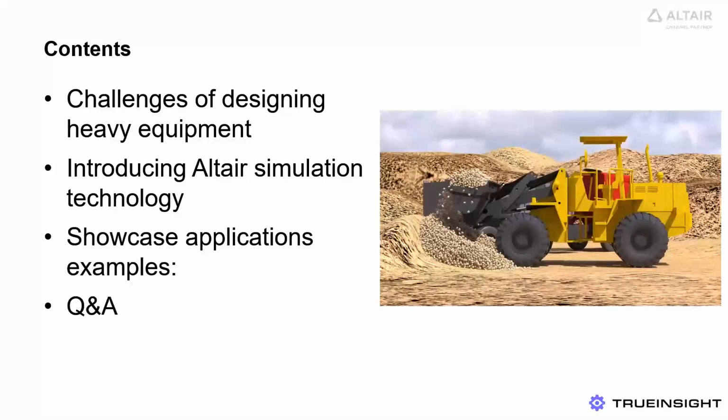Traditionally, most of the bulk materials handling and processing operations, including mobile equipment, are empirically designed, and the measurements of input data into models, such as force and pressure on equipment, are difficult to obtain, time-consuming, and costly. Typical bulk material problems faced include blockage, material buildup, equipment downtime from broken parts, and equipment wear, that all ultimately lead to lower productivity.